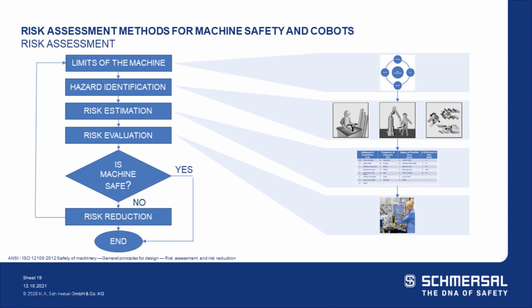Now, technically at this point, when you've done those four, it's actually called a risk analysis. We haven't technically done a risk assessment, right? A lot of times we use the term risk assessment loosely. A risk assessment actually does the HRN one more time, but with the guarding on.